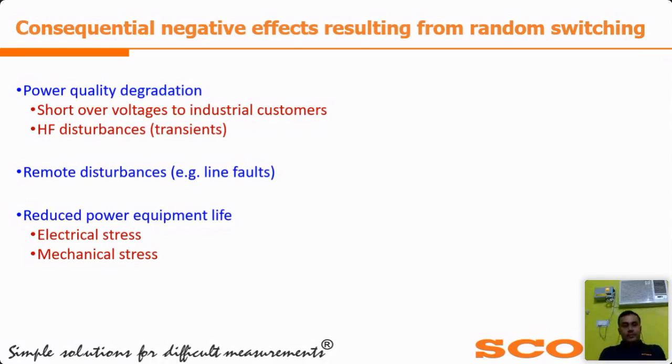Like at the time of closing, due to high inrush current, there may be some electromechanical stress inside the core that may hamper the winding insulations. The next one is mechanical stress, because there is an electromechanical force due to the inrush current. It may arise some mechanical stress on the electrical windings also.